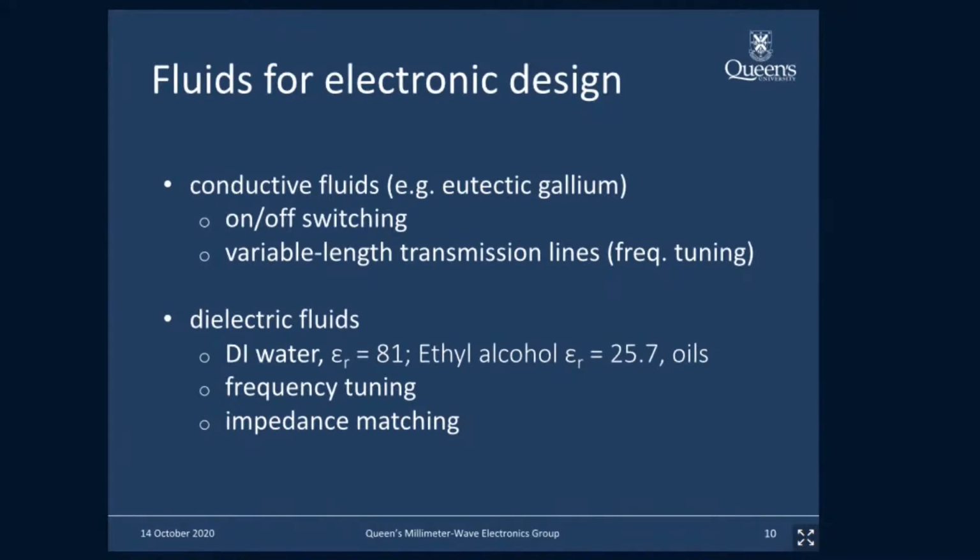There has been work on tuning antennas with semiconductor devices, but again, there are some limitations there, particularly with respect to power handling of the semiconductor device. Keep in mind that antennas are, of course, at the front end of a wireless system, and for, say, transmission, you're usually transmitting a good amount of power, so linearity is actually very important. And again, semiconductor devices bring that limitation with them.